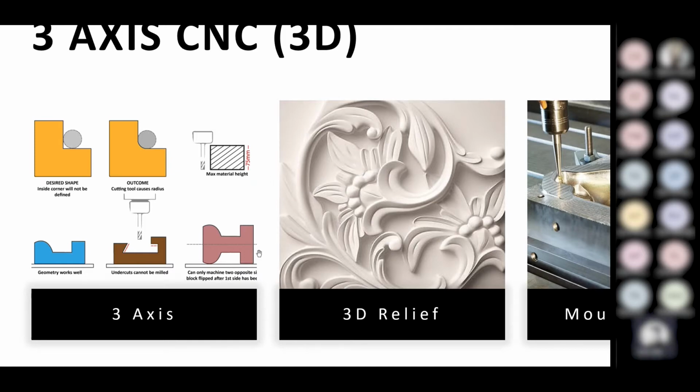But there are some issues that you're going to run across even then. So for instance, things like undercuts are really common. Let's say, for instance, we've laid this object down. I can see that it's got a bit of a shelf to it, or what we call an undercut. Where this CNC machine can only plunge on the X, Y, and Z axis, it can't get underneath that area. So instead, where it's got this cut coming down here, we'd actually just do that just straight down.